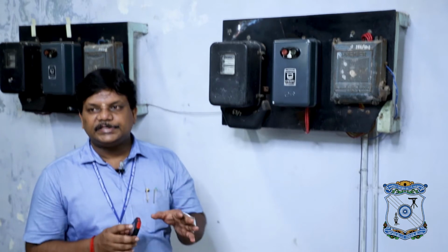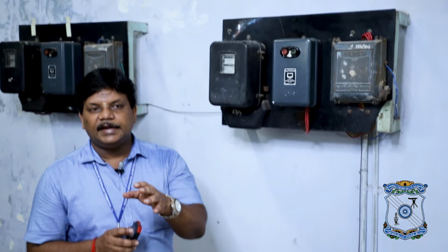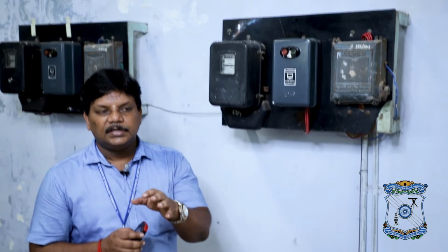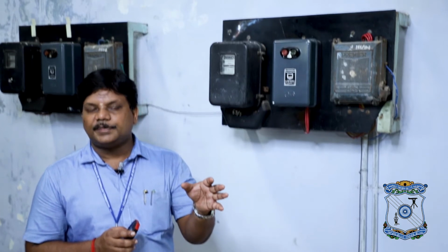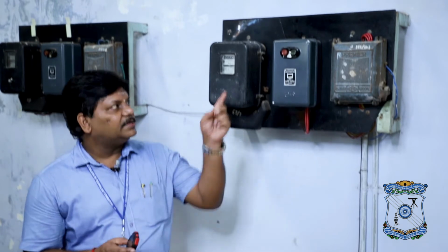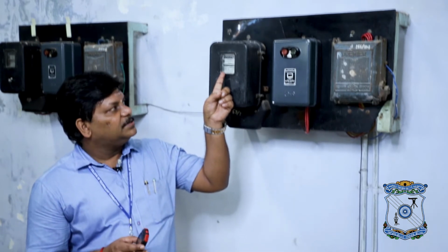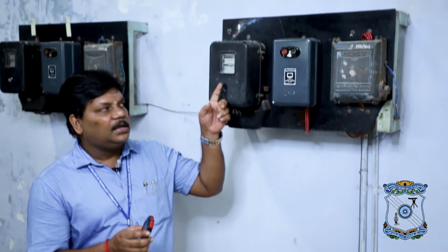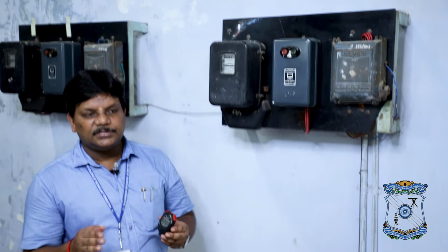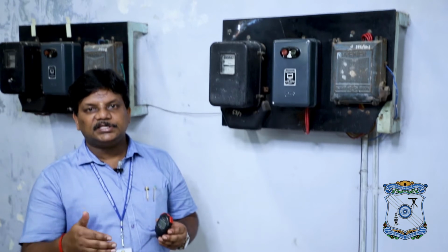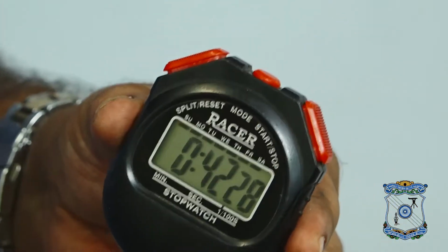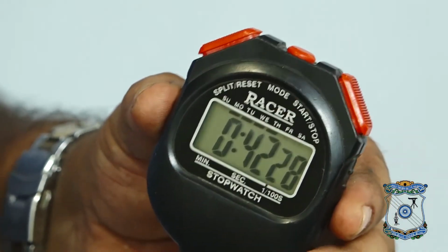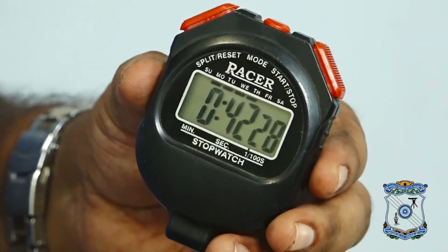So far we have measured the static head, then the delivery head, then the orifice is already known to us, then we have varied the speed. The speed is now around 1750 rpm, and we measure the energy meter time for 5 revolutions. These are the things you have to repeat for further increase in speed. You have to increase by either 100 or 200 rpm, from 1750 to 2000, maybe 1950, then 2200, 2400 and 2600.